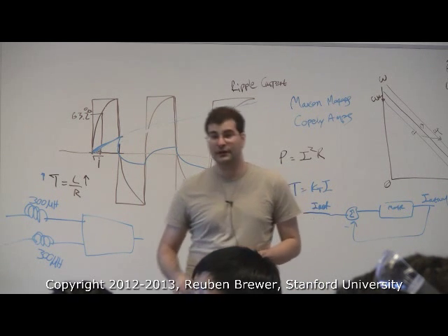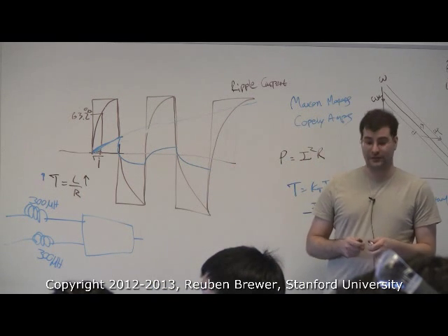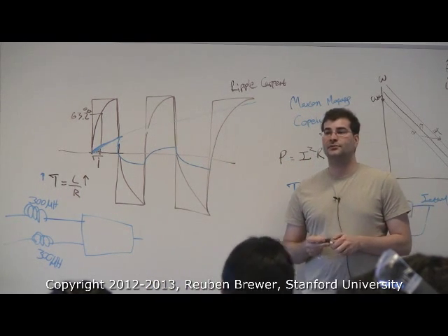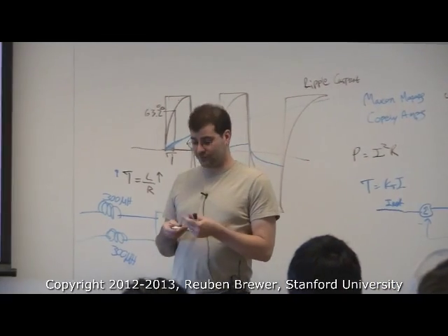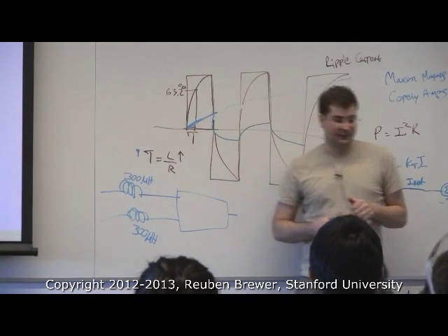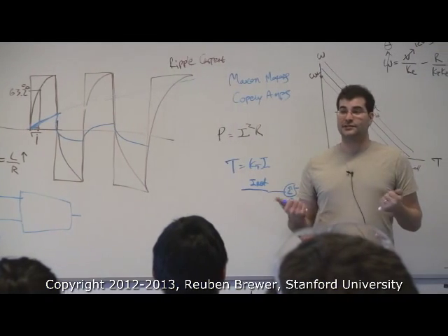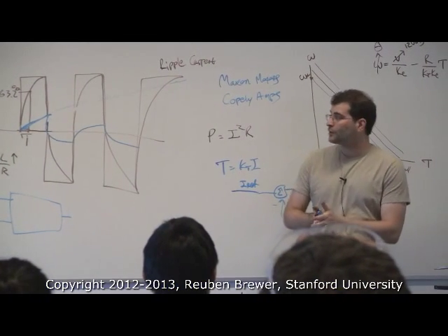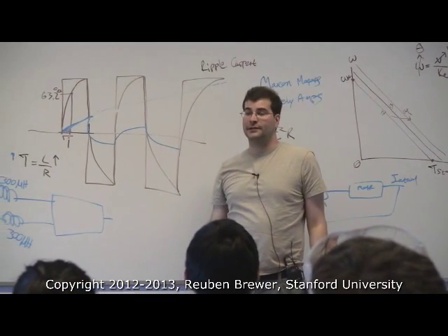It reduces the performance of the motor. It's speed. Let me ask you a question about reducing the performance. If you don't add the inductance, but you need a Maxon motor and a Copley amp, and it goes unstable and sets your motor on fire, is that performance good or bad? I would say it's unacceptable. You are correct. We are slowing down our motor electrical dynamics, right?